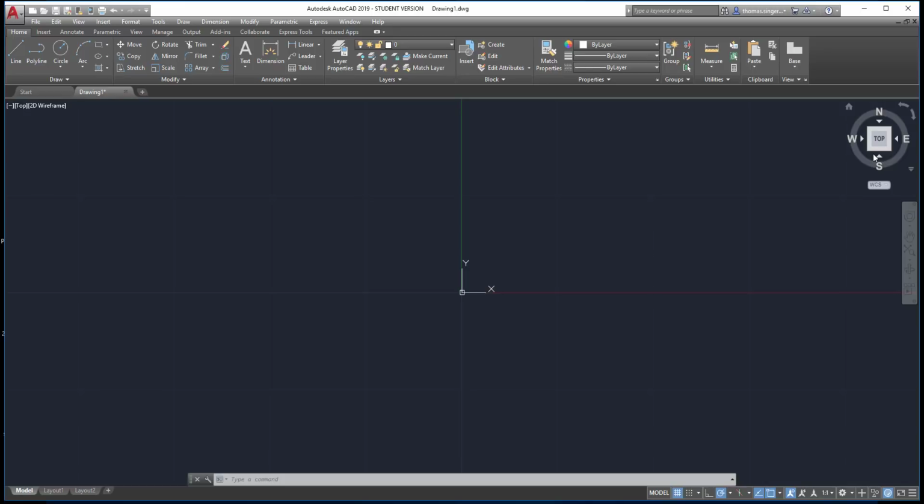And this is a consistent tool that you're going to see on almost all the Autodesk products. Once you learn how to use the basics of the view cube, you can grab a corner and rotate it. There's a lot of different things you can do with it. Just to give you an idea of how to utilize it, you can rotate it by using the ring around the outside. But in essence, it's fastest just to click on the side or the corner to get the view itself.